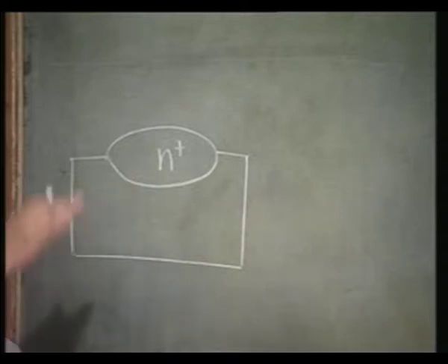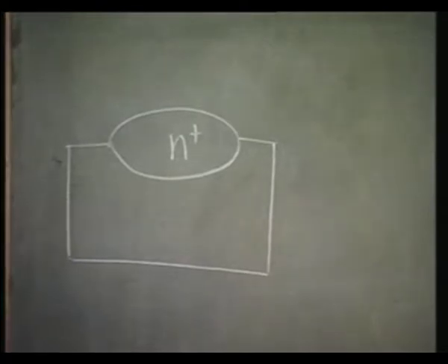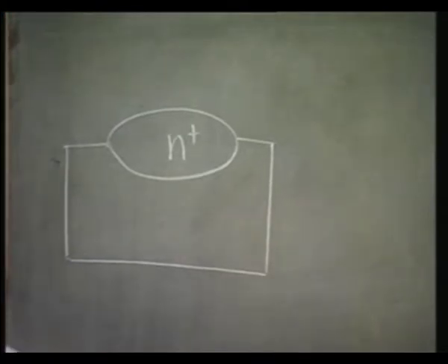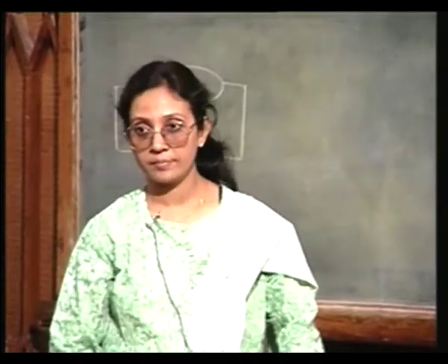Up to this, it is identical to the older bipolar junction transistor technology. The difference is after this. Now, instead of having an n epi layer, you have a p epitaxial layer.